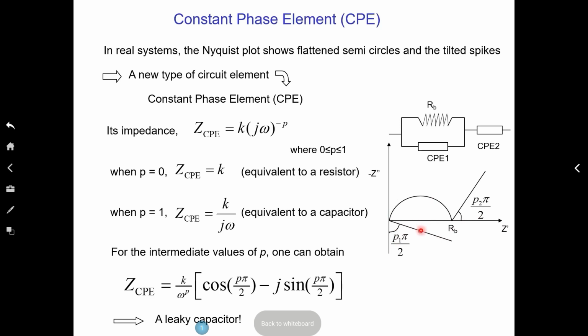So this angle, depending on how much deviation, can represent heterogeneity in the microstructure of the sample itself. For example, you have a polycrystalline sample, and you have a huge, large grain size distribution. That will be reflected in making the angle larger and larger.